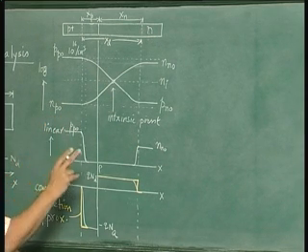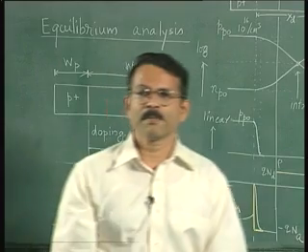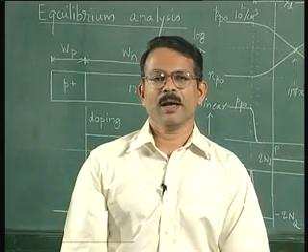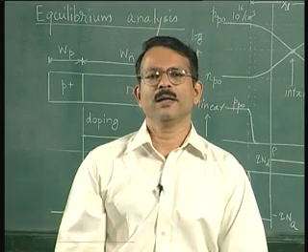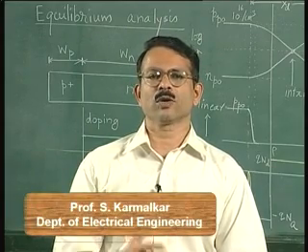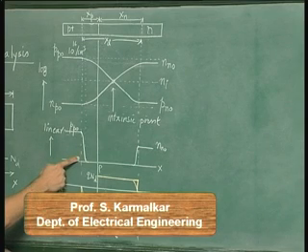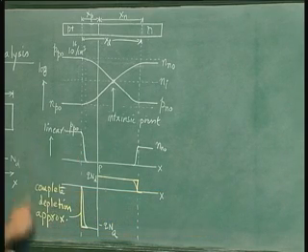So to explain the validity of the depletion approximation, it is more useful to see the linear scale. And in fact, the log scale may give a wrong picture. It may try to give an idea that the depletion approximation is very crude. But when you see the linear scale, then you know that the depletion approximation is actually quite good.